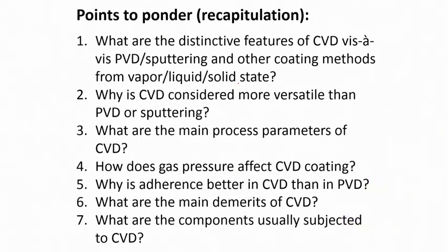All kinds of cutting tool inserts, semiconductor devices, ceramic components, all moving parts which require a very thin, hard, high elastic modulus surface are ideal for such coatings by chemical vapor deposition.